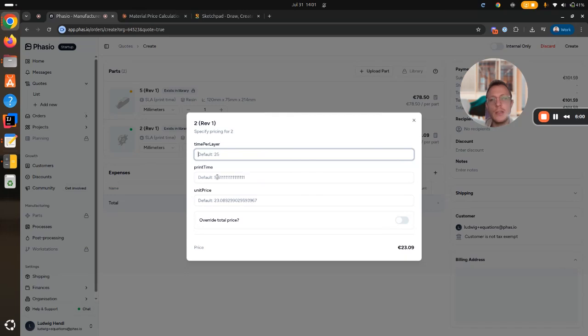And just as a side note here, this is now an even print time per layer, right? What you could also do to make your algorithm more complex, and this algorithm is just a start, you could think about varying the time per layer based on the aspect ratio, for example. That is something where the laser in an SLA machine takes more time to cure the resin everywhere.